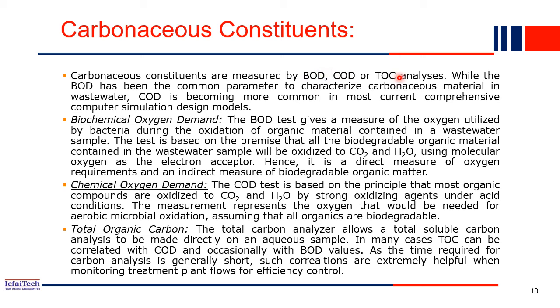So based on this quantity, again we can classify the wastewater, how much it is, whether it is good quality or bad quality. While BOD is the common parameter, we always perform the BOD in the wastewater. BOD will give us an indication of how much pollution is present in the water. The BOD experiment is nothing but finding out how much oxygen demand is there in the water.